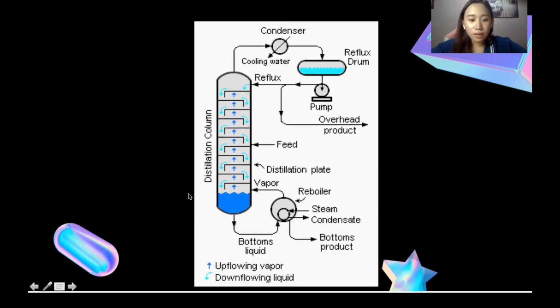This one right here is the vertical shell. The vertical shell holds the column internals, which may be the plates or trays or the packing. So this one is those column internals. And then we have the reboiler in here on the bottom side, which vaporizes the components. And then at the top we have the condenser here, which cools and condenses the vapor leaving on the top here.